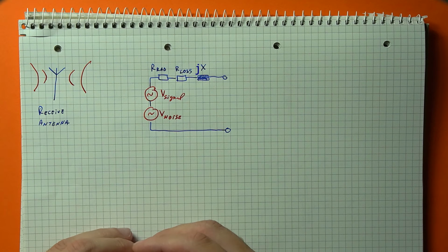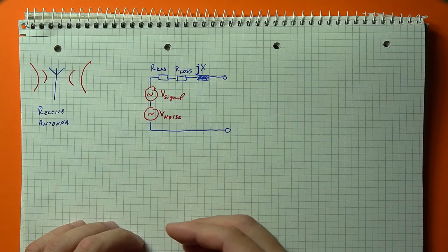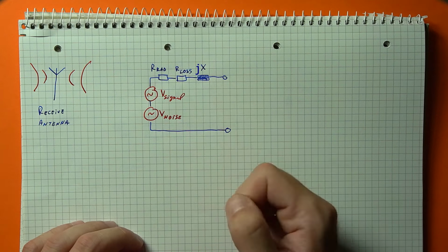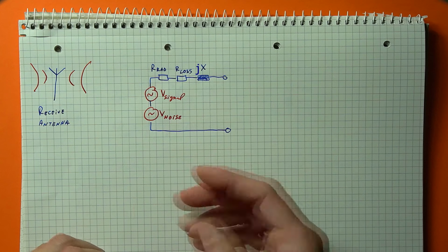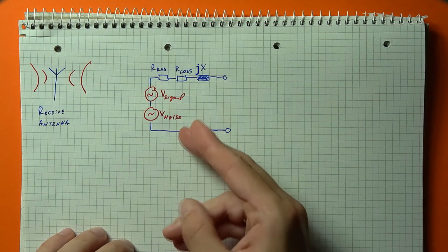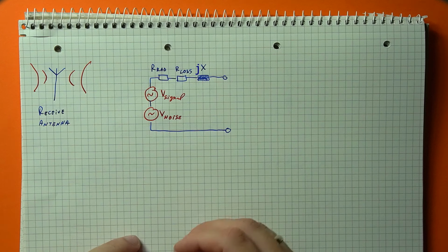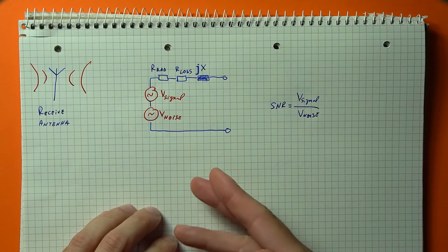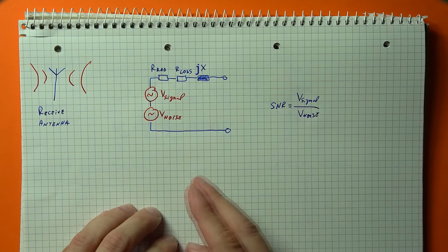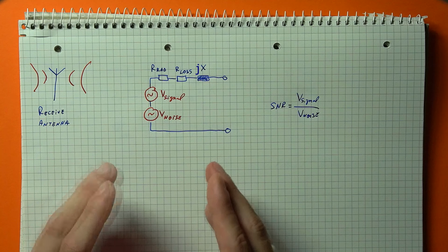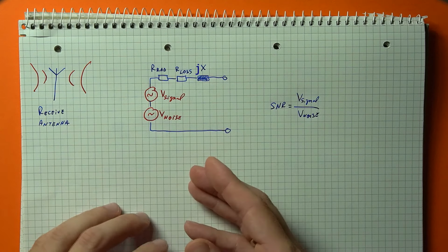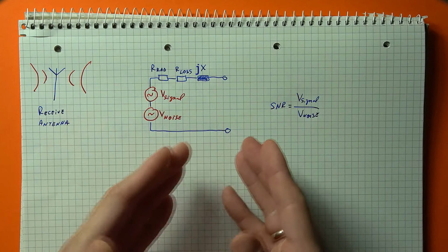What makes the reception case so special? So a complete antenna model for reception can look something like this. You have your two resistive bits, the reactive bit, and then you have the incoming signal, and then a noise source. This can be further detailed if needed. Now, this noise can come from the environment, but also from the construction of the antenna, namely its resistance. The significance of taking into account the noise becomes apparent when observing the signal-to-noise ratio. If you ignore the noise, it does not matter what impedance the antenna has, since you can always perform matching and half of the input signal will reach the receiver.